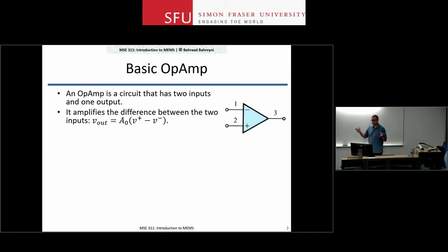But then the temperature variations come into play, and then the differences between devices and the differences between resistors and all those things. So you get a spread. You get a distribution for your, let's say, bias point values. But with op-amps, that's not the case. Usually, you buy an op-amp, and if you're not pushing that op-amp to its limits of performance, you get more or less the same behavior, whether you make 1 or 2 or 10 of those circuits.